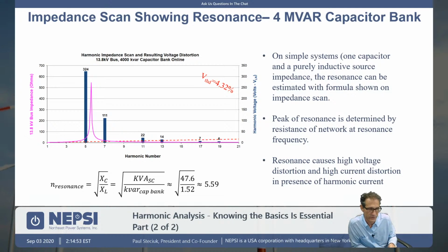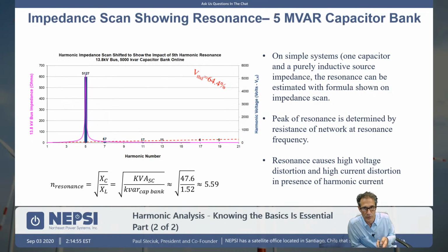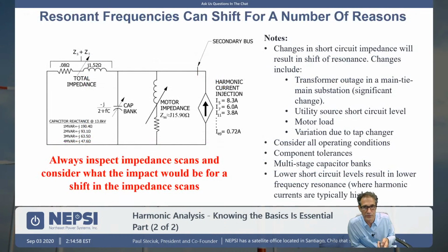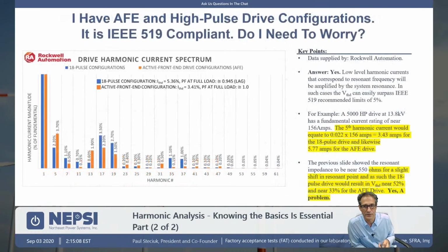You still may have issues. And when you do your analysis, you should be doing a sensitivity analysis to make sure that any type of shift in your impedance curve or in your resonance will not result in an operating condition that is not good.